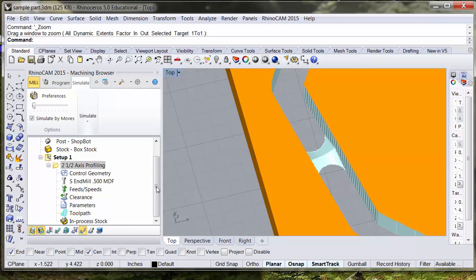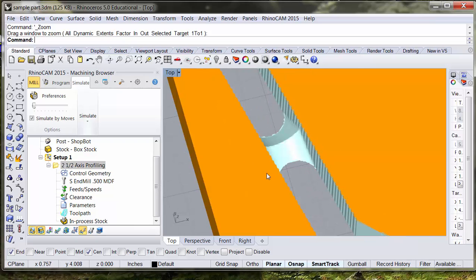or something like that. The other cautionary piece here is if your tabs are too small and you miss your Z height and you're cutting into the table on that last pass, some of the bulk of the tab can end up being cut into the table itself and not being on your part, which means your part is free to kick loose and hit the cutter. So that's something important to think about when you're doing tabs.